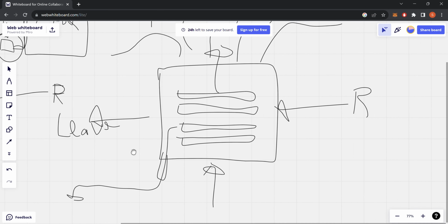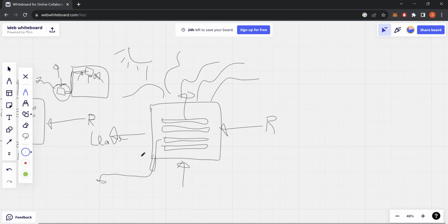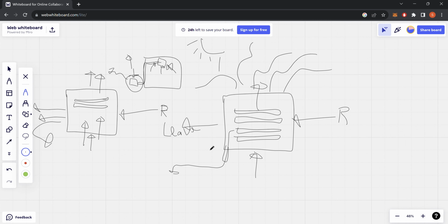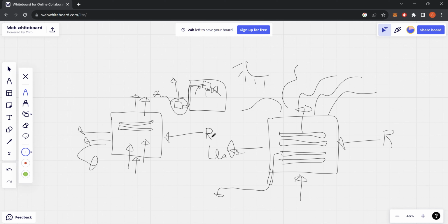And that is something that's continuously happening. Now what this is doing, in the right proportions, is dehumidifying your house. If you have a bunch of humid air, all that humidity is going to collect on these lines, and it's going to drip out of the house, right? So that's why the air that comes out of your vents when you're running AC is cool and relatively comfortably dry. So those are multiple things that are going on here in the evaporator. So that's the basic function there.